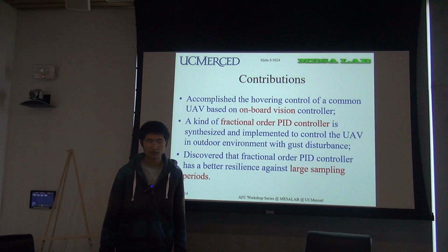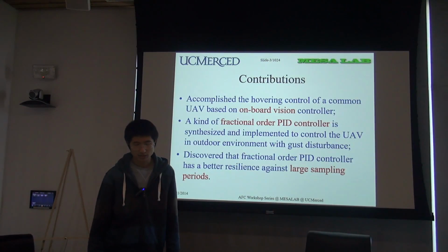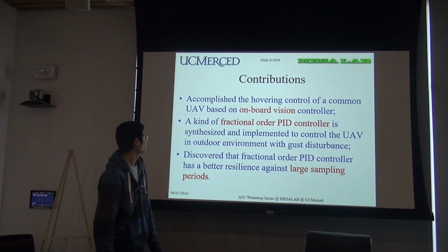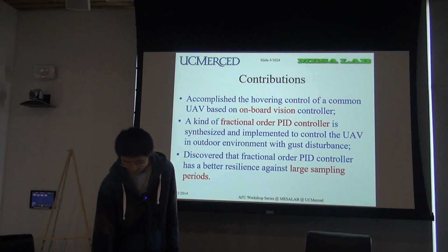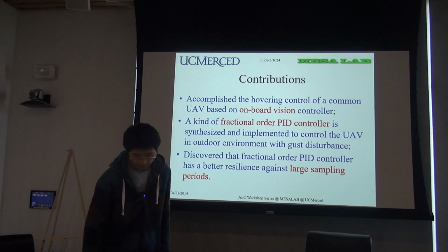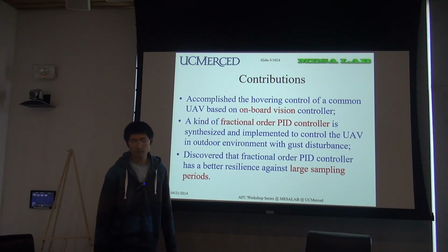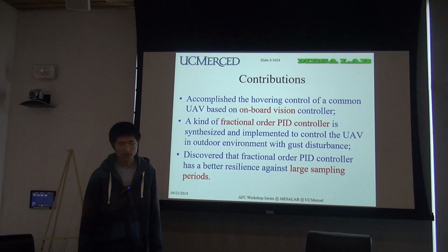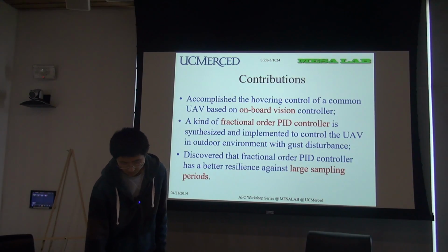We use a fractional order PID controller to control the UAV. In this way, it can fly more robustly, especially in outdoor environments with gas disturbance. We discovered that the fractional order PID controller has a better resilience against a large sampling period. This may be the first time.